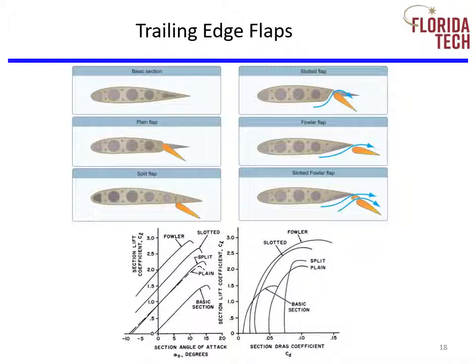The Fowler flap arrangement is similar to the slotted flap. However, when extended, it lowers and translates aft, thus increasing wing area as well as camber. Because of the unique movement of this type of flap, the mechanism is quite heavy and complicated and therefore may not be practical for certain aircraft applications.